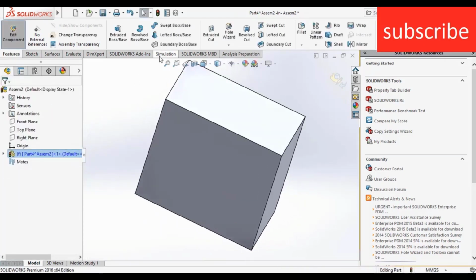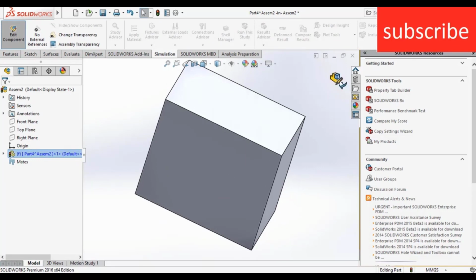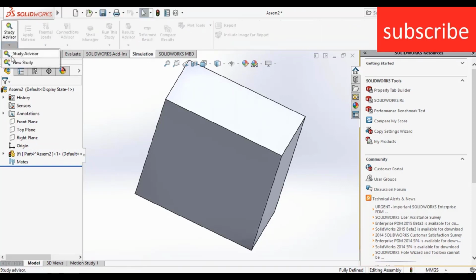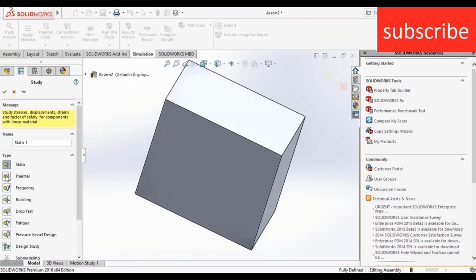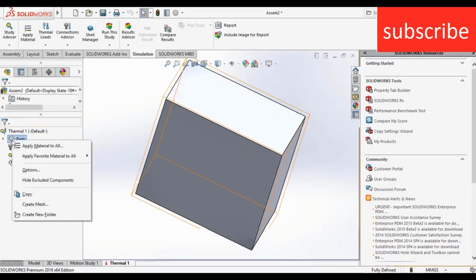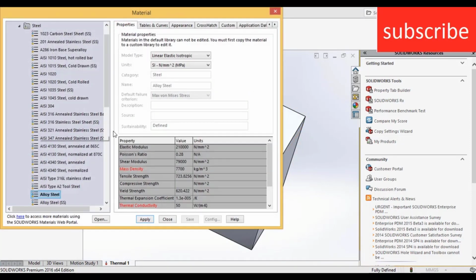Now go to simulation. First exit the edit component. After that, go to simulation, click on new study, click on thermal, click OK, right click on parts, click on apply material. Now select the material as per your requirement. Make sure you check that the thermal conductivity value is given.